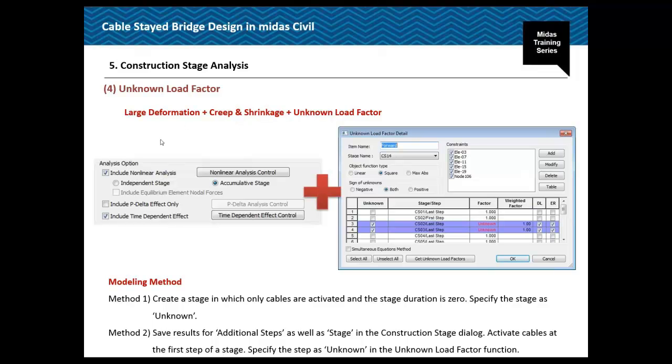Actually, in the previous version, we could not consider the large deformation effect with the unknown load factor, but in the latest released version, I mean the version that you are currently using, we can now consider the large deformation effect and the creep and shrinkage unknown load factor at the same time.